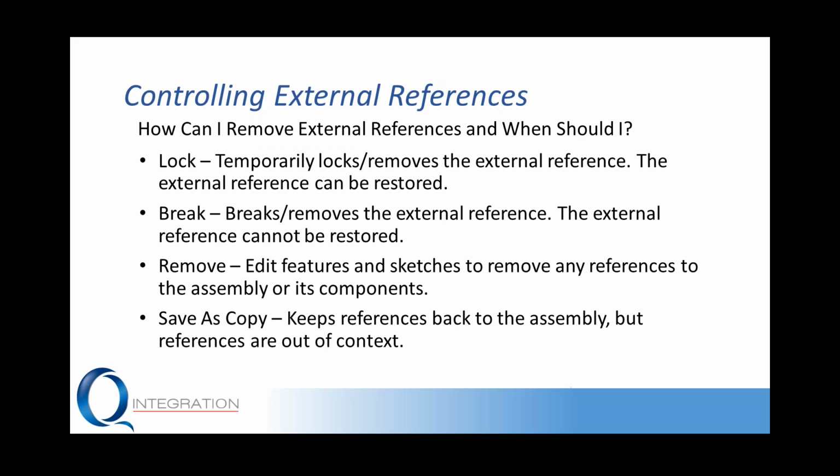Another way to do this is to save as copy. So if I perform a save as copy, the file is still referencing back to the assembly, but those references are out of context, and I no longer see any of the changes to that assembly.